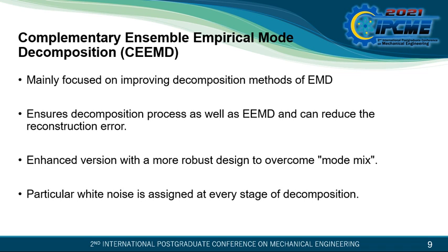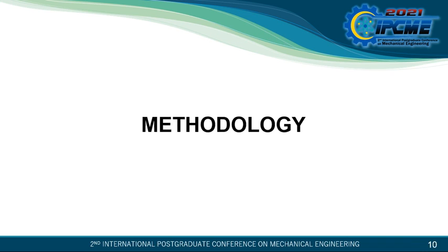The Complementary Ensemble Empirical Mode Decomposition (CEEMD) method mainly focuses on improving the original decomposition method, that is EMD. This next generation of EMD ensures the decomposition process as well as EEMD and can reduce the reconstruction error. It is also an enhanced version with a more robust design to overcome the mode mixing problem. The CEEMD method implements a particular white noise at every stage of the decomposition process.